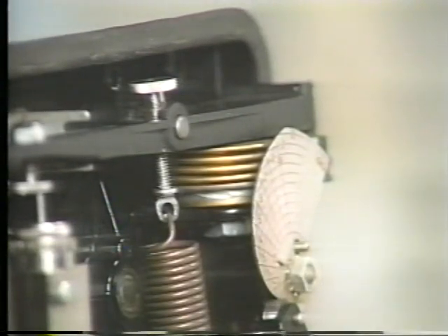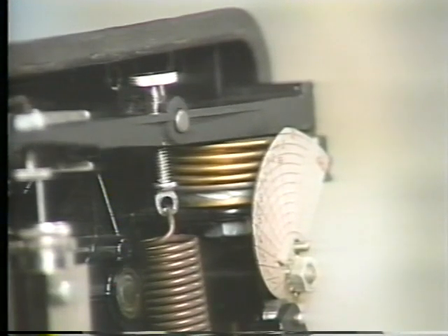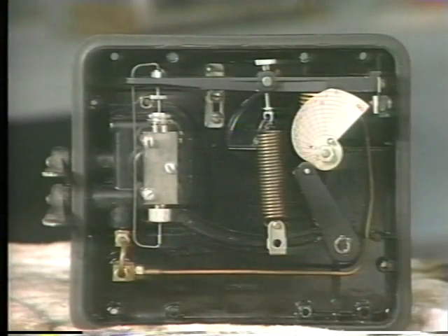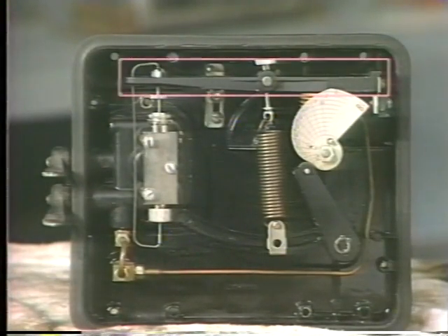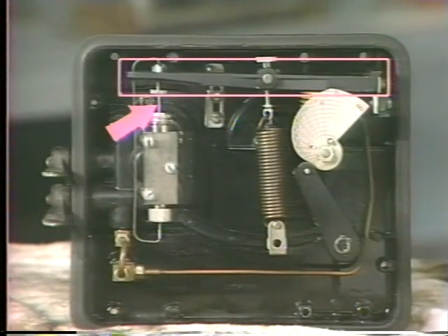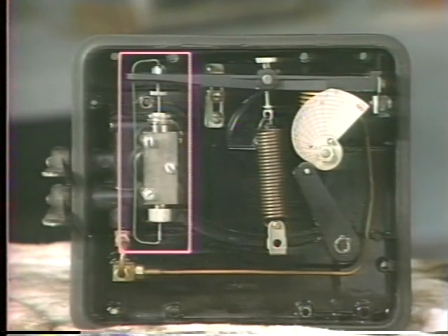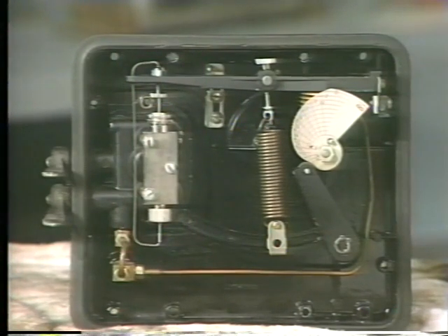When the positioner receives a control air pressure signal from a controller, the control air enters the input bellows. Remember, this signal from the controller is meant to correct an error in a process variable. The bellows converts the force of the control air pressure into motion by expanding when the control signal is increased and contracting when the control signal is reduced. As the bellows expands and contracts, it pivots the balance beam, which moves the pilot valve stem. Now, it's the pilot valve that directs air pressure to an actuator. We can use a simplified illustration to see how.